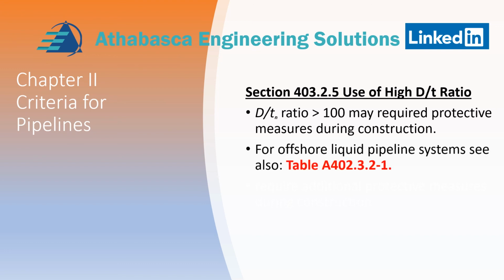But anyways, there is another section here for offshore liquid pipeline systems, and they have a table in their respective section, A402.3.2.1, where they have special rules on the high D over T ratio.